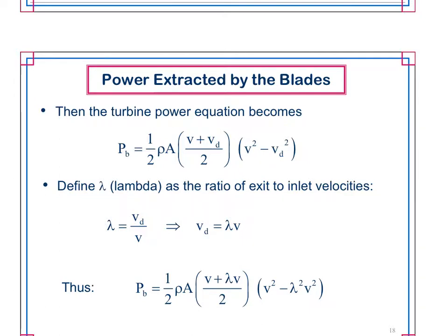And our equation to calculate our maximum efficiency will use this, except we've got some additional v squareds in there, and these equations are not super useful. What would be useful is to figure out some ratio of downstream to upstream wind speed, to see how fast the wind has dropped, or what value the wind has dropped to. Then we can use that to calculate the maximum theoretical efficiency. Once we know the best case scenario for dropping the speed of the wind, we can calculate what the maximum efficiency is going to be.